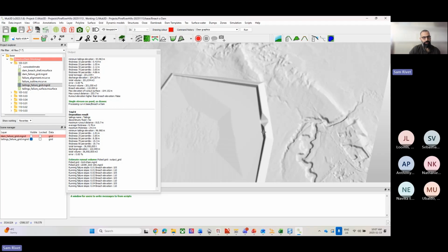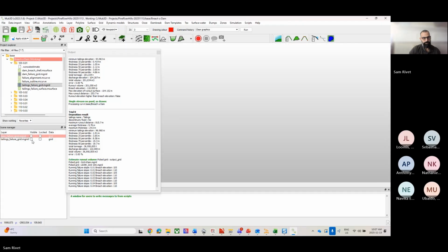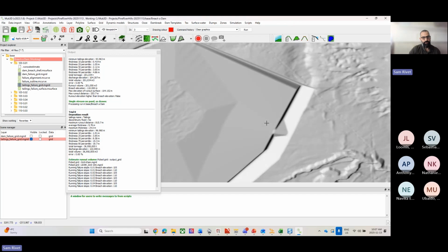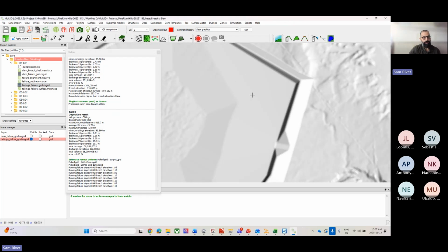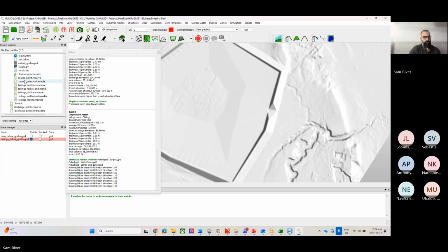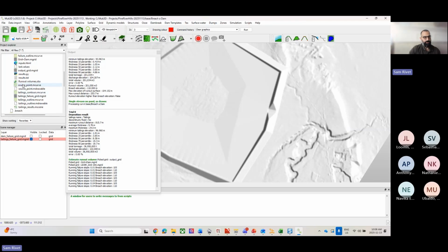So it's showing you how the tailings failed and how that dam failed, with your tailings failure grid essentially having the failure components of the retaining structure and of the tailings within it. But we don't see where it went. You have this for every option. So you don't see where the tailings went with this tool, but you see how it failed within the facility. And it's summarized in this Excel sheet that I'll just open up right now.